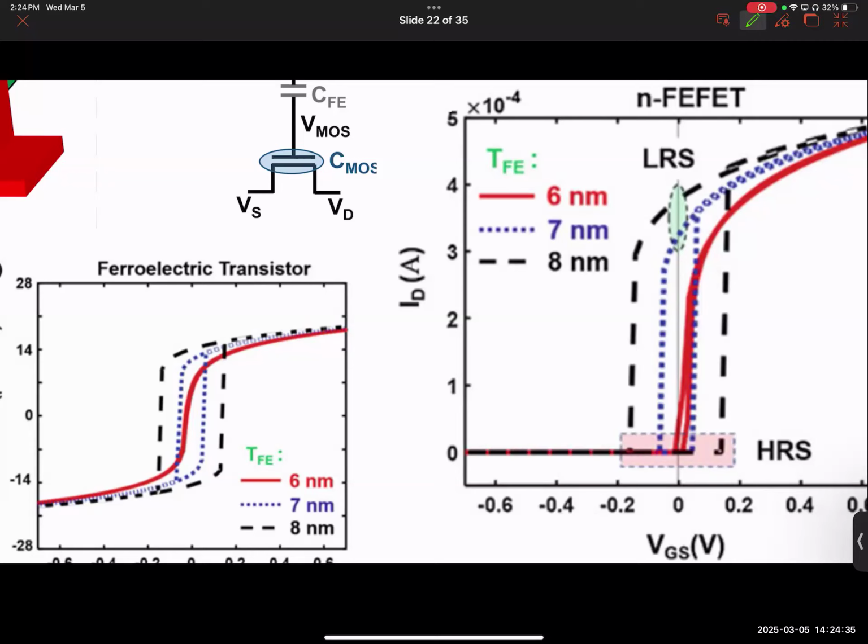Okay. First point is, notice, so there are two curves, right? One is this one and the other one is this one. Both are green here, but you see one of them, look at 0 volt. 0 volt means it's off. Even when it is off, one of them has a really high current compared to the other one. That means it will be leaking like crazy. Does that make sense, folks? And did I tell you that leakage is a problem?